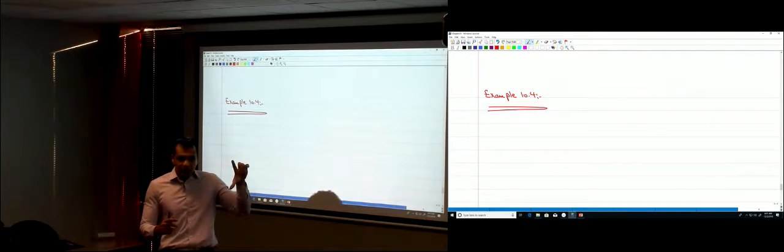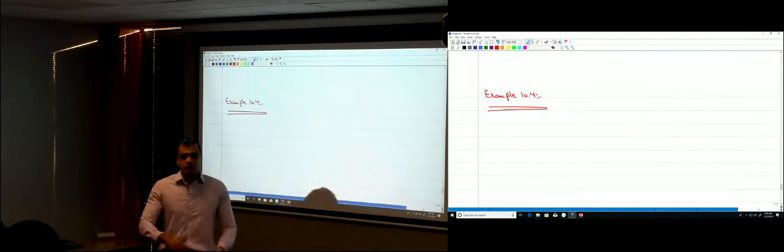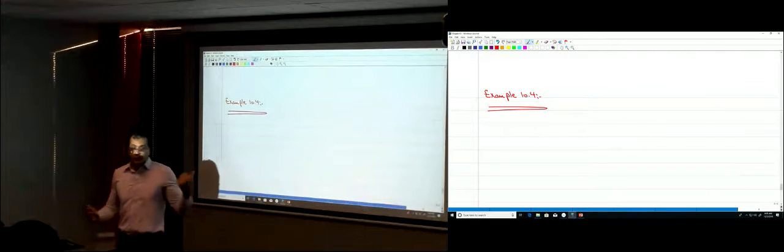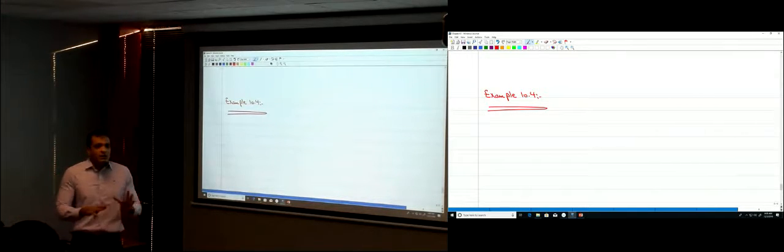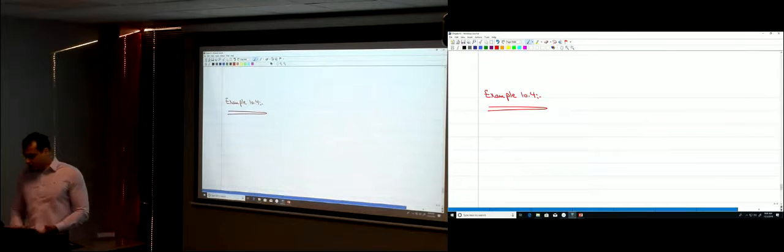You assume the depth of the beam equal to the span divided by 10, and then the width is equal to 1/2 that value, right? And then now you have the dimensions, you design for the area steel, right? That's what we're going to do now in example 10.4. You have nothing, so you're going to have to assume or find some dimensions, and then find area steel according to what we did in example 10.3.